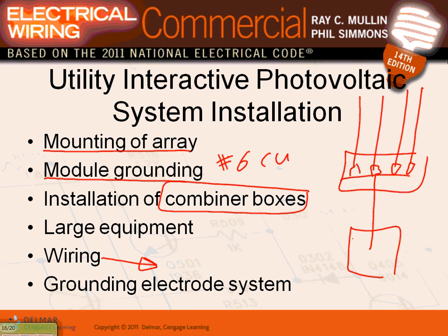There's a couple of wiring methods listed in the NEC code book that we use. THHN here, THWN. THWN is one of them that you can use for AC or DC. USE-2. These are wiring methods on the DC or the AC side.